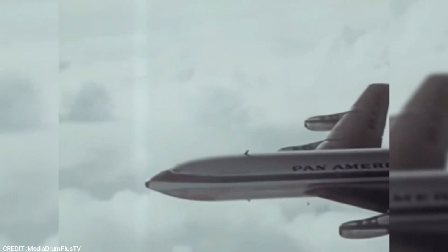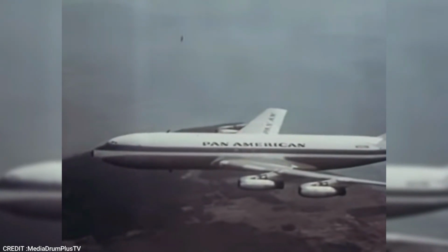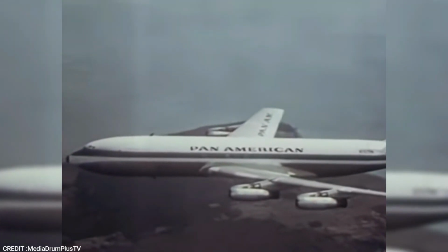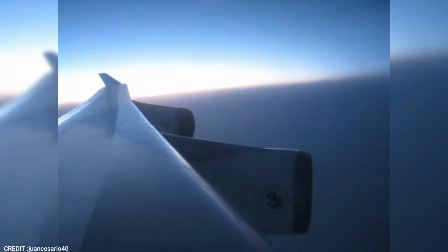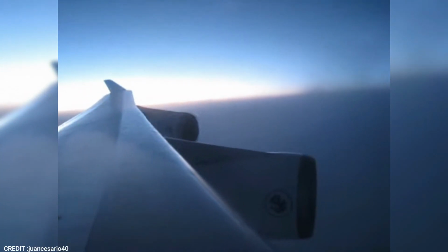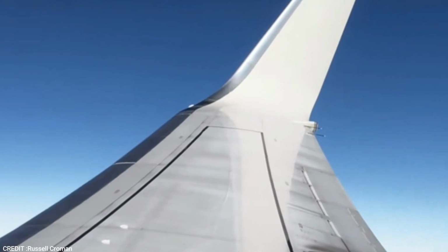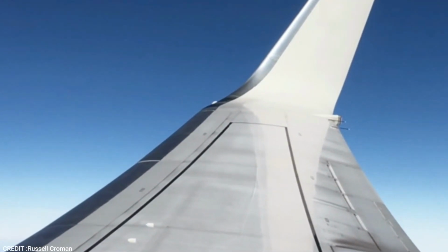With the advent of jet airplanes in the 1950s, pushing speeds close to and beyond the speed of sound, airfoil and wing shapes made another dramatic change. Thinner airfoils allowed subsonic airplanes to fly closer to the speed of sound before encountering adverse shock waves over the wings. Shock waves greatly increase the drag and reduce the lift.